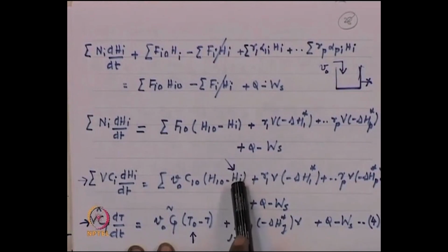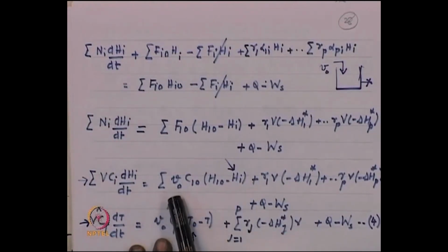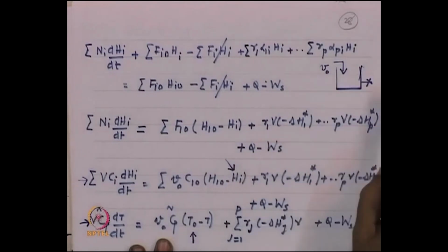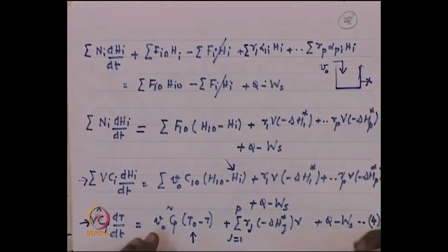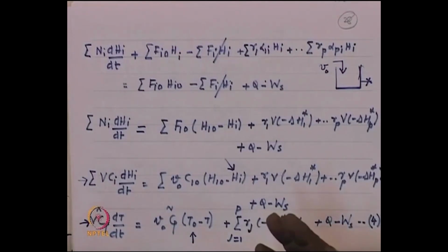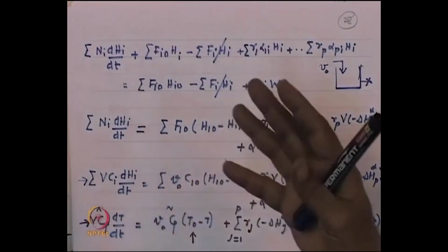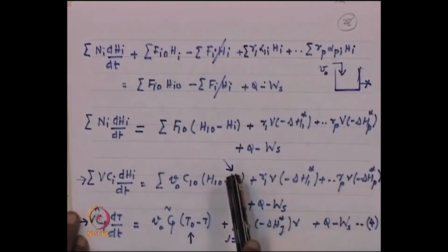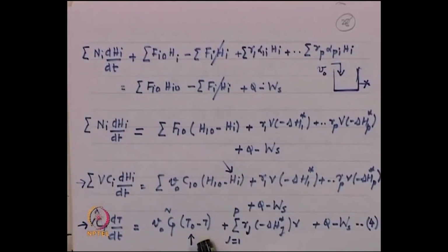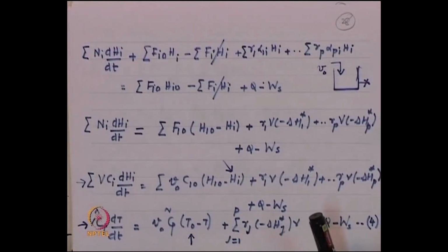H I is the enthalpy of the stream in the equipment. So, see, it is multiplied by V naught, not V naught is input, not output. Is that clear? So, you should be very careful in a given exercise how the equations play out in your application. Otherwise, you might knock out terms which are actually not appropriate to be knocked out.